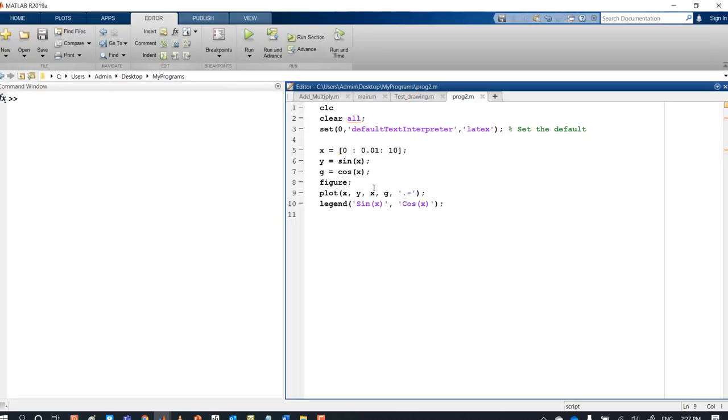So here, actually, you can plot the XY and XG together. There is another way of doing it. Let me show you another way. Figure, let's try the following. If I would like to say plot X and Y only, I can say hold on, and then I can say plot X and G, and maybe I can make this red dash dot.